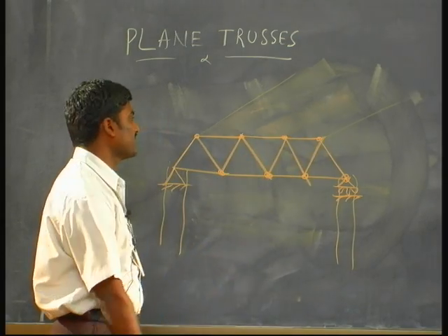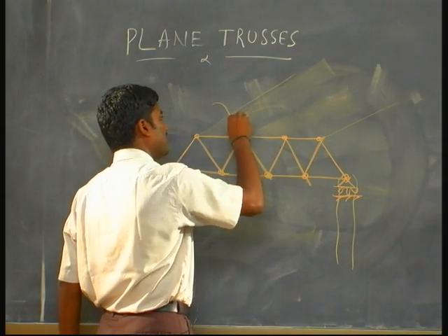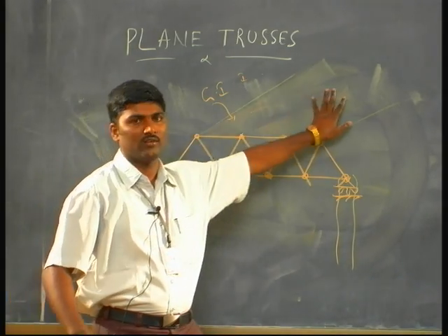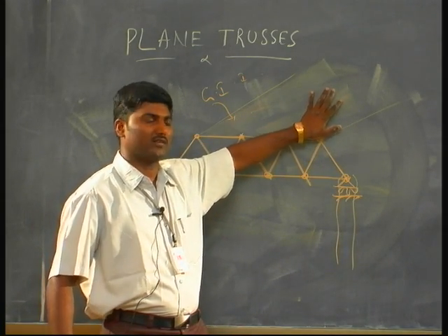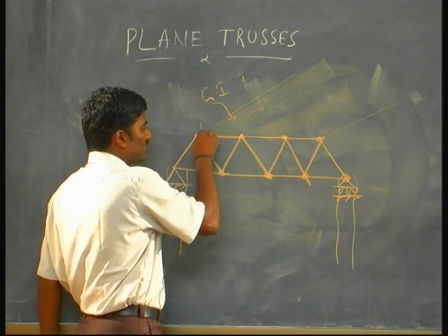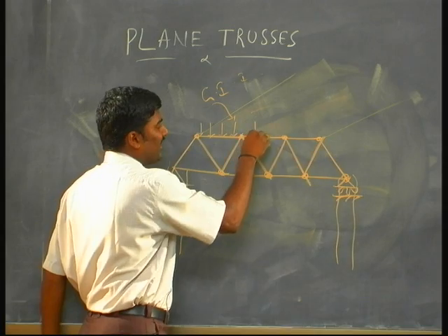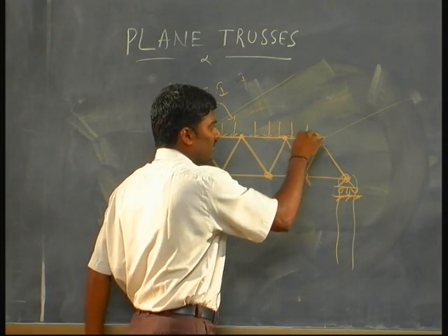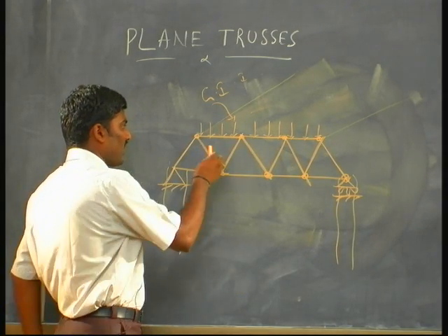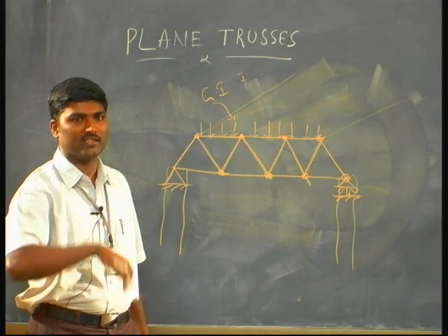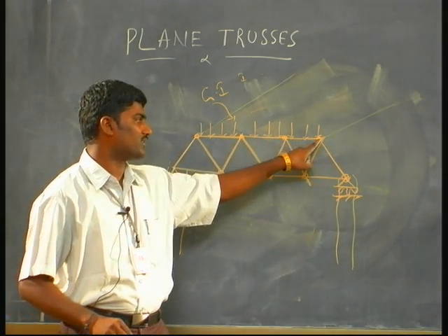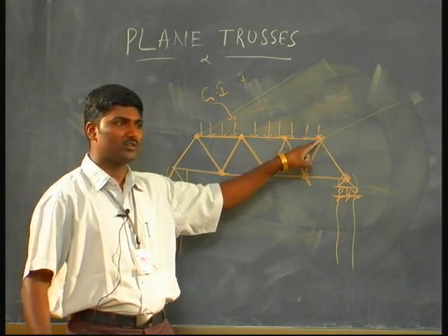All these effects must be protected against by providing a roof covering material. The roof covering material can be a GI sheet, an iron sheet, whatever you place, that will be roofing material. From the roofing material we will get the loads at the top. The weight of the roofing material itself is the force coming onto the truss. My assumption is to have loads only on joints, I should not have loads on the member.